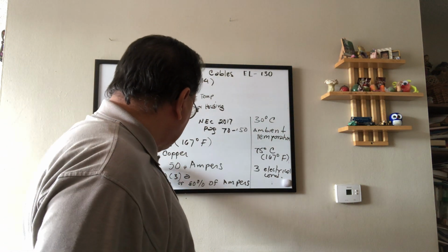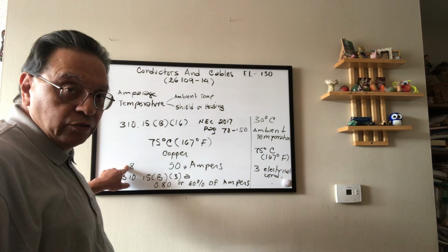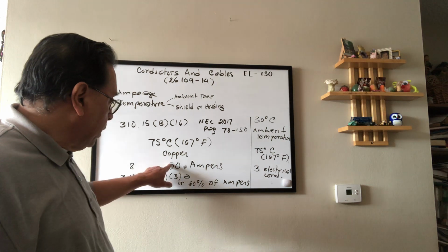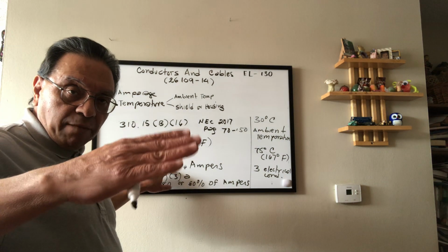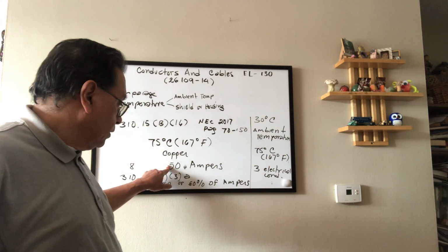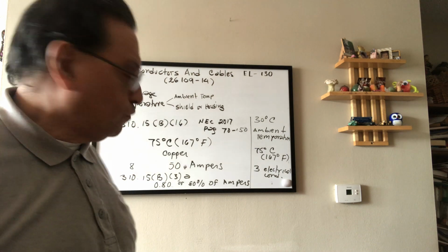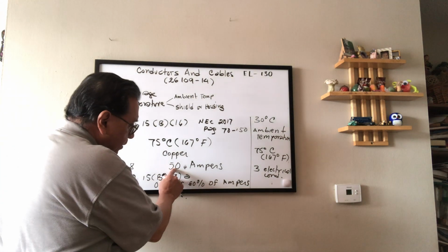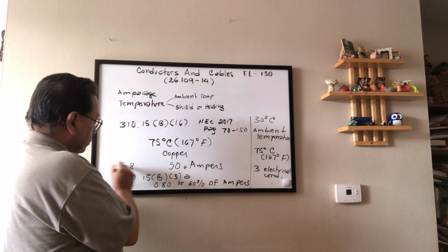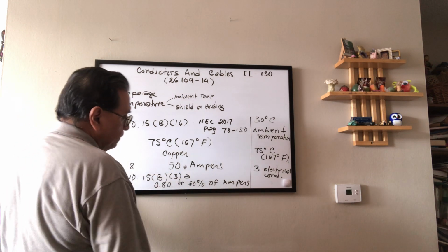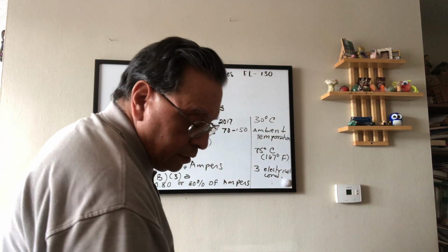So in reality, these electrical conductors under this condition will be able to transport 40. Their capacity is reduced, instead of 50, to 40. So I multiply the nominal amperage that this electrical conductor is able to transport times 0.8. So that will give me 40.